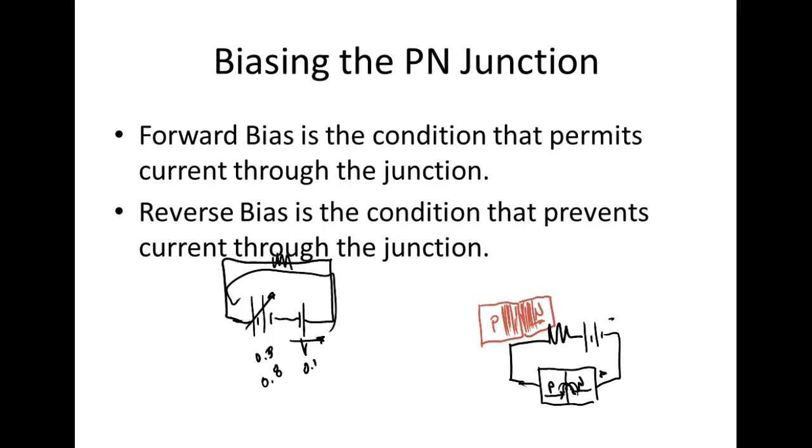We call it leakage current. And that'll be part of your data sheets. They'll tell you the leakage current as a function of temperature. So now we've got a switch that I can control electronically. Instead of me going up there and doing what? Flipping the switch, we can control this guy electronically. Forward bias, it acts like a what? Closed switch. Reverse bias, it acts like an open switch.